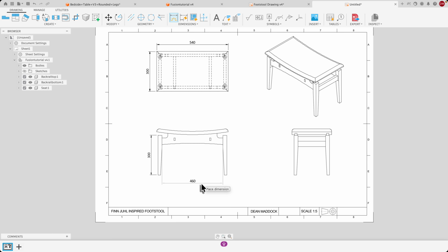So unfortunately, it's not going to snap to something that looks similar to this. So we're going to have to do it visually. Also, the leader lines are much longer than we would normally have. So around about there is good. And we can put in the radius lines. And also the other dimension that we might want is the length of this component here. And we'd like that to line up with that. We just have to do it visually.